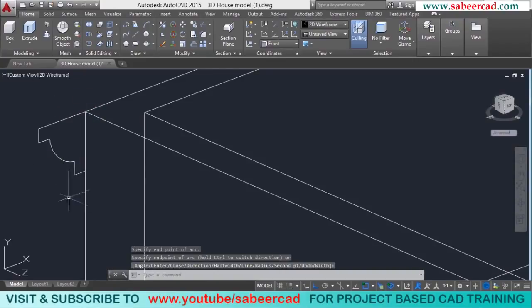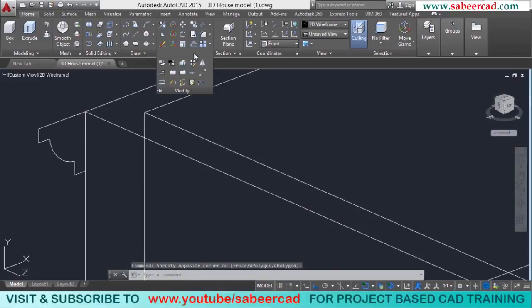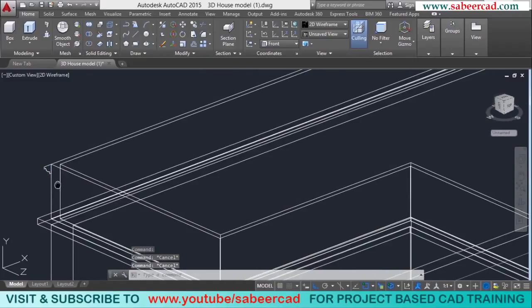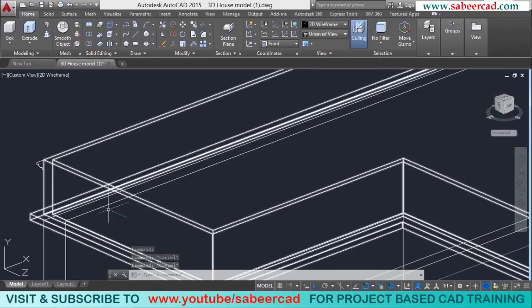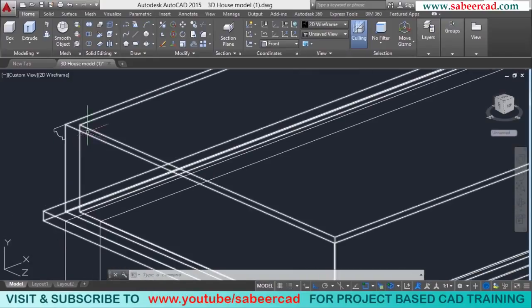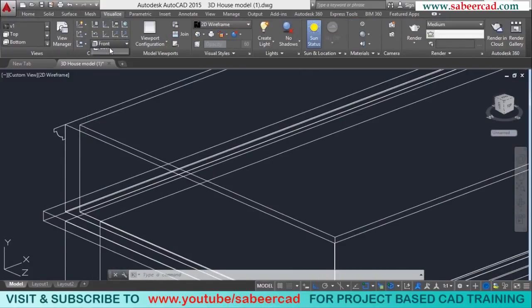Now I'm going to join these profiles as a single profile using the join command. So I'll click on the modify panel and I'll select join and I'll select these two profiles. Now it is converted as a single profile. Next, I'll draw a polyline path along which this profile can be extruded. But before I create the path, I should align the UCS back to the world coordinate setup. So I'll click on Visualize tab and I'll select world.